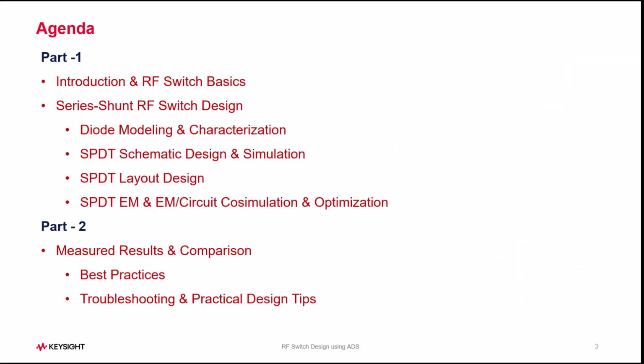Now, keeping time consideration in mind, I have decided to split this video into a two-part tutorial. In the first part, which is this video, we will start with RF switch basics and then walk through a complete step-by-step design process of doing an SPDT switch design, ending with EM circuit co-simulation and co-optimization.